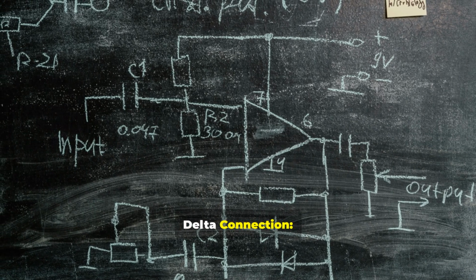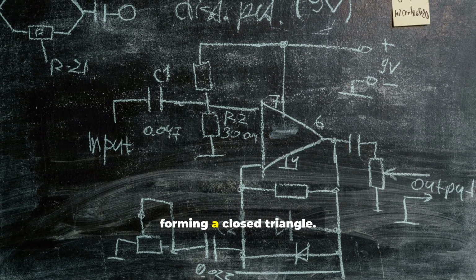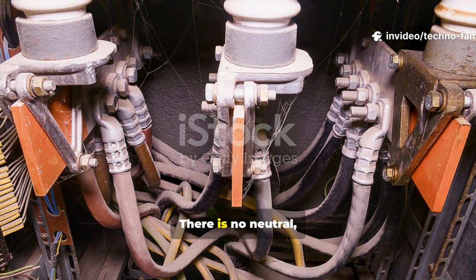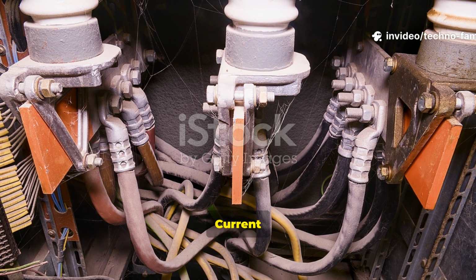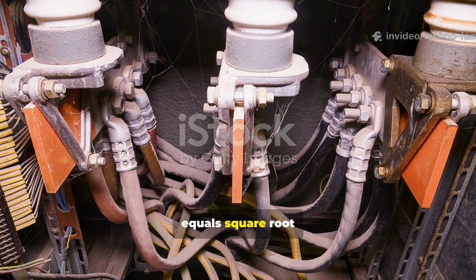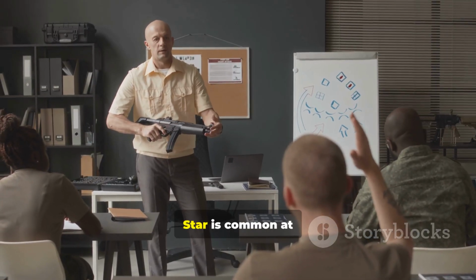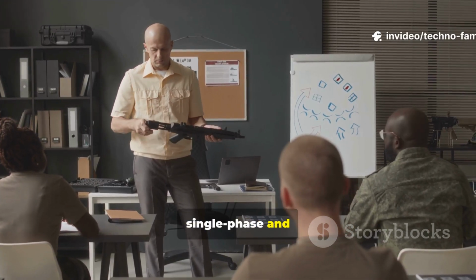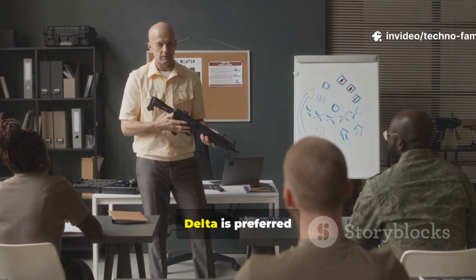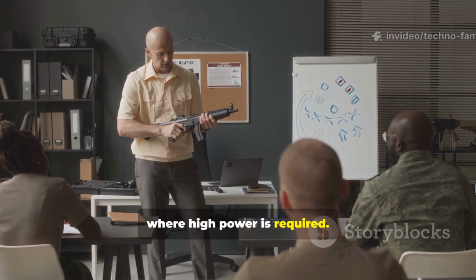Delta connection. In delta, the ends of the windings are connected in a loop, forming a closed triangle. There is no neutral, and line voltage is equal to phase voltage. Current relationship is IL equals square root of 3 times IF. Where do we use them? Star is common at the consumer end because we can provide both single-phase and three-phase loads. Delta is preferred in transmission and for induction motors, where high power is required.